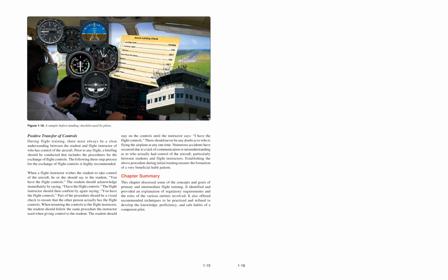Figure 118. A sample before landing checklist used by pilots. Positive transfer of controls during flight training. There must always be a clear understanding between the student and flight instructor of who has control of the aircraft. Prior to any flight, a briefing should be conducted that includes the procedures for the exchange of flight controls. The following three-step process for the exchange of flight controls is highly recommended.